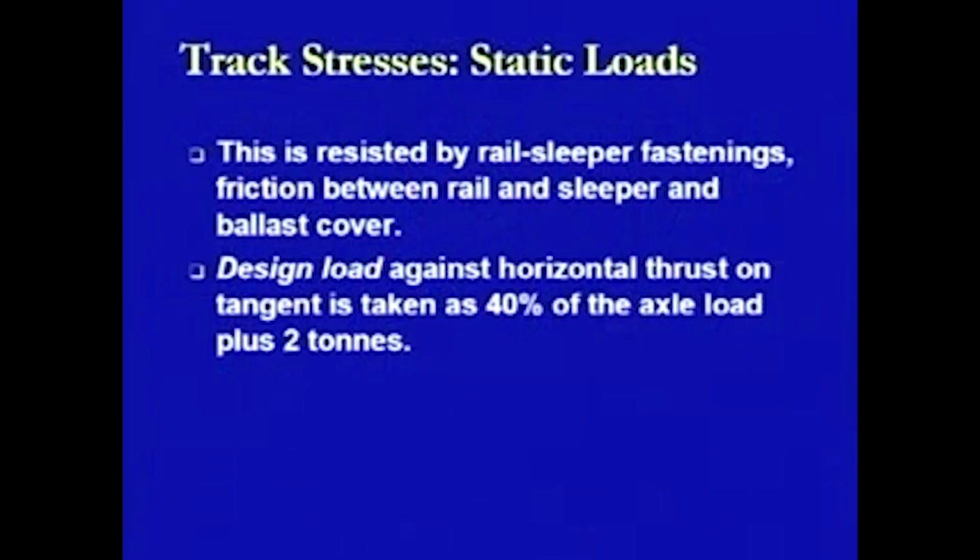Now, when we are talking about all these lateral forces, as we have just seen that there can be a twisting or bending condition at the foot of the rail section, it is going to be resisted by certain fastenings by which the rail section is fastened to the sleeper. And therefore, the total amount of this load is going to be transferred to those fastenings.